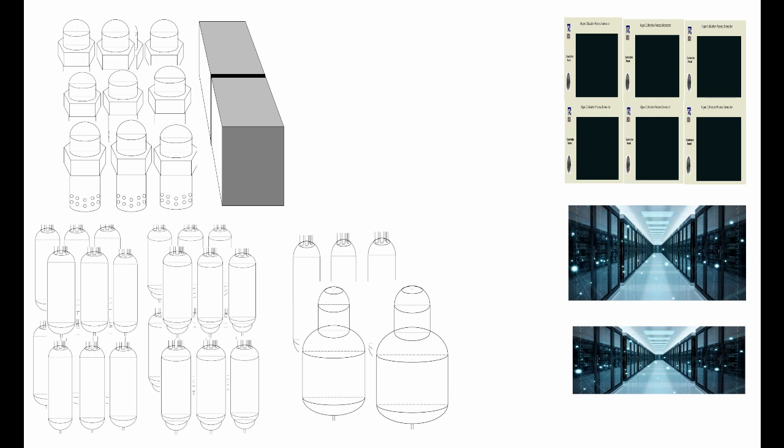At the outlet, the digestate flows out of the digester bioreactor system as a slurry, taking with it a minimal amount of the fluid. The slurry flows into a downstream grinder where the particles are pureed and fed into the fermentation bioreactors.